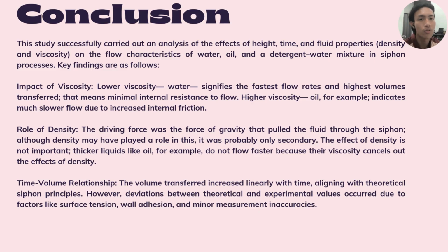Conclusion: this study successfully carried out an analysis of the effects of height, time and fluid properties on the flow characteristics of water, oil, and detergent water mixture in the siphon process. Key findings are as follows. Impact of viscosity. Low viscosity water signifies the fastest flow rates and highest volumes transferred. That means minimal internal resistance to flow. High viscosity, which is oil, indicates much lower flow due to increased internal friction.